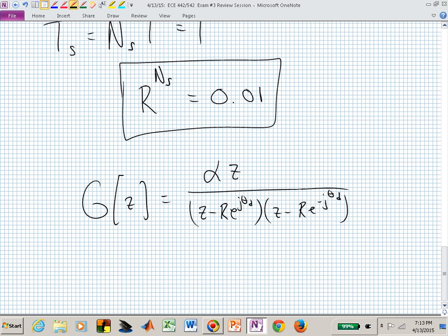It's this pole-zero excess idea where you have now 2 in the denominator and 1 in the numerator. Now you just have a one sample period delay net if you have the z there. You have 2 if it's not there. And we're not going to probably worry too much about that. And at z equal to 1, having the zero at the origin doesn't mess up your DC gain calculation. Yes?